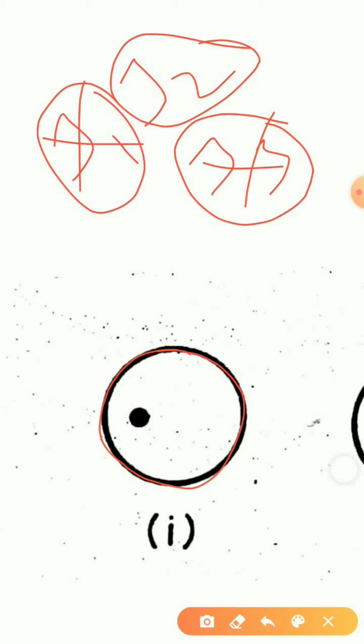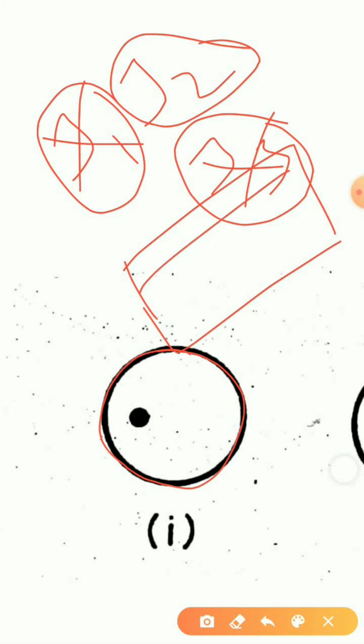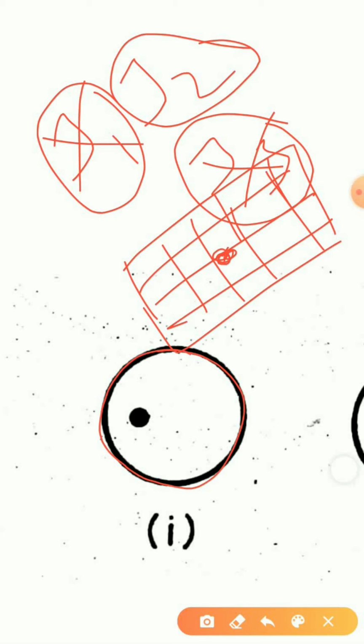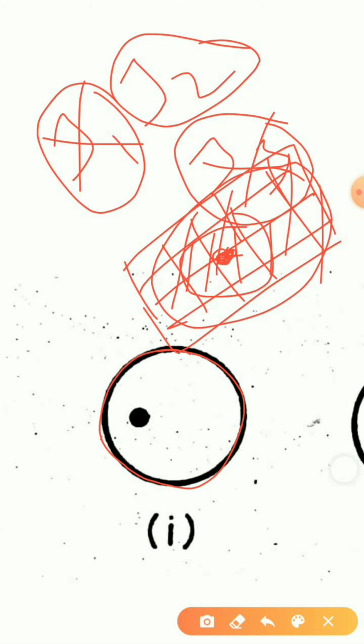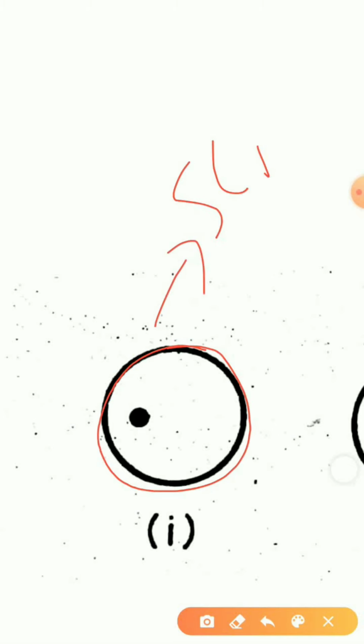The current flow is like in a dam, for example: if a dam's wall has to rupture, it has to start from one point. From this point water will start gushing out, then slowly this will rupture the other parts, then the whole dam structure will collapse. In a similar manner, here we can see that this is the full cross section of my SCR's junction J2.